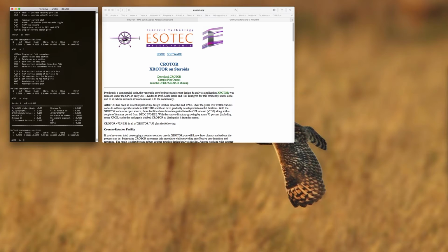As I mentioned, we're just going to use some simple propellers that are using the same airfoil cross section across the entire radius of the propeller, even though the chord length is going to change. You can add some additional aerodynamic sections in here and define different propeller airfoils that will perform differently. And the reason that this is typically pretty important is since the propeller is a rotating airfoil, you end up with a variety of different Reynolds numbers across that range of props.